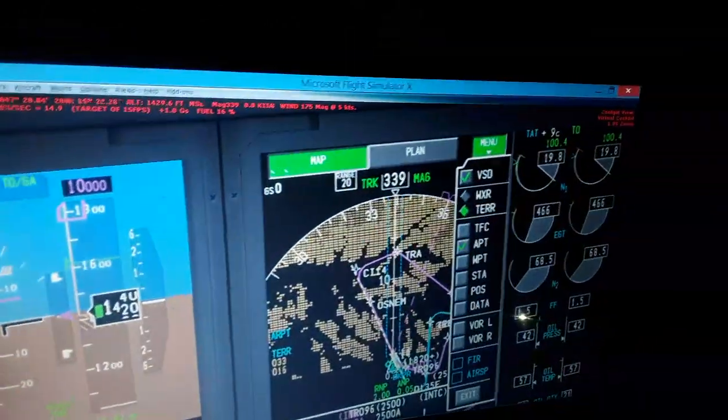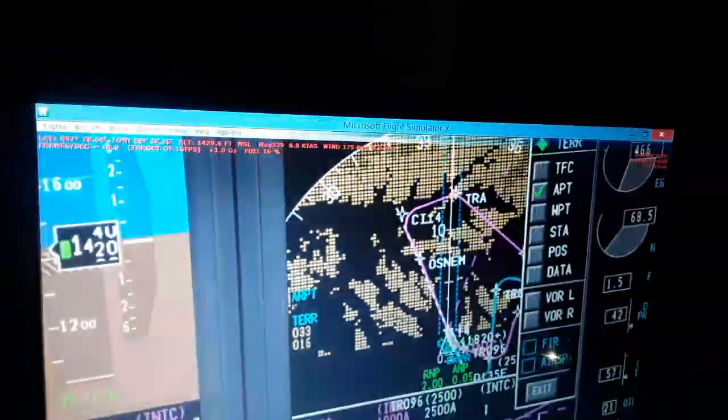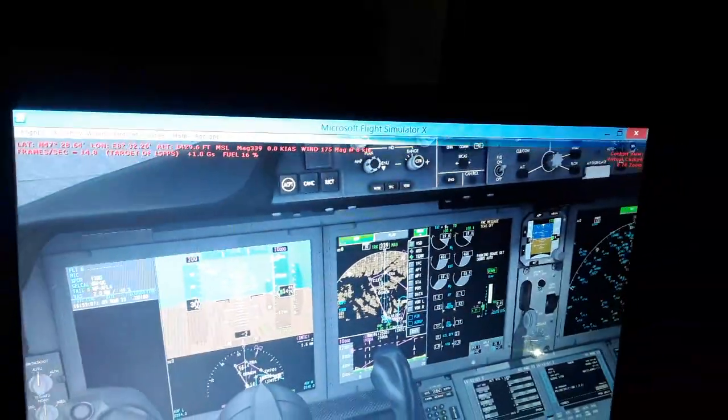Also, we're gonna set the altitude here, the target altitude. You can see the flight plan here from takeoff. Cruise, we have to cruise through some waypoints here we have selected using the flight management computer.